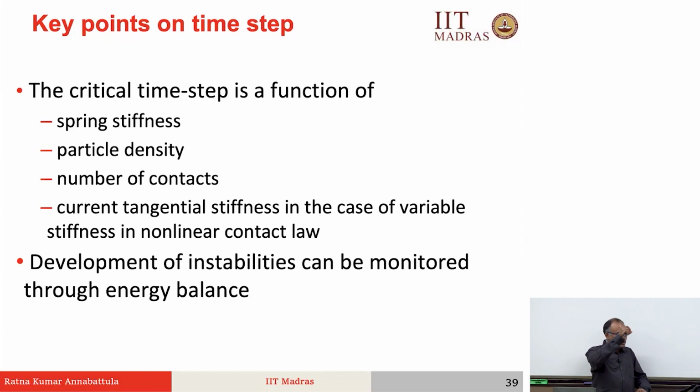The particle density will not change, it is a fundamental material property. When we are talking about soil, we are actually talking about the soil particle. So, soil particle density is what I am talking about. The density of the soil particle will not change, but the soil assembly density will change when you are compacting, because the gaps are changing.